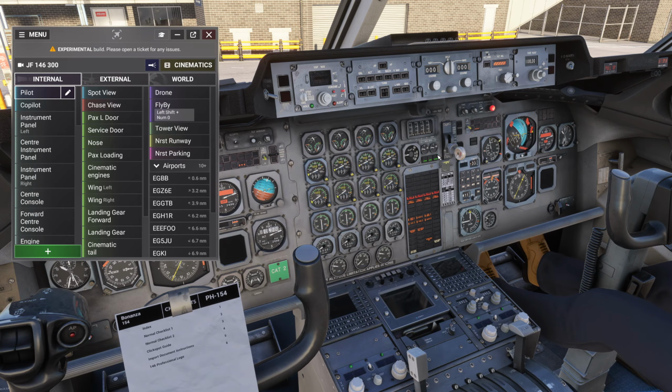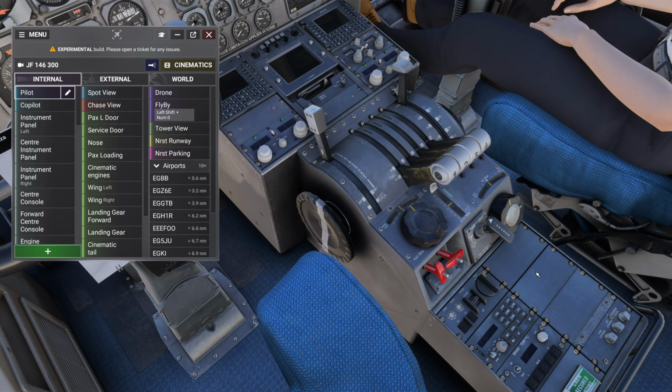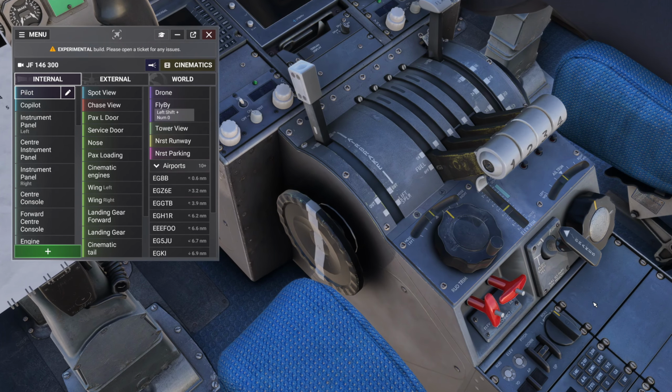Next, let's ensure the brake system is in the yellow range and that the parking brake is set. Once you've got that confirmed, we'll move on to the next step. Okay, yellow and parking brake set. Make it shorter, please. So, short items, please. Understood. Next, master switches for yaw damper, autopilot, and avionics on.